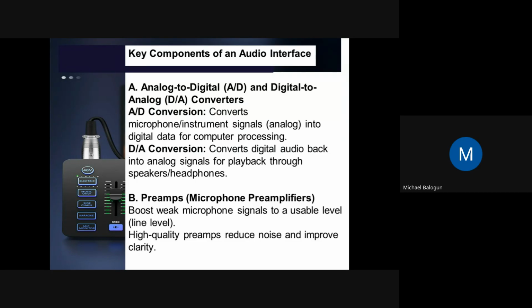The lower the quality of your preamp, the more noise it's going to bring up. In some places, some people bring out their sound card and it's very clean, but you introduce your own preamp. By the time you turn up the knobs, you begin to hear hum, noise, and all of that. So you need to increase the signal to noise ratio. You have to drop your own preamp, and wherever you're getting your source from, you tell them to help you out.